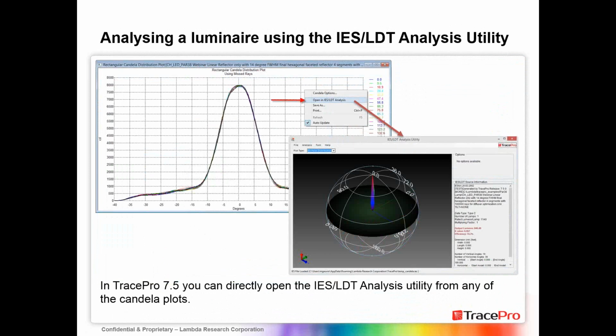Now, there's something new in TracePro 7.5. This allows you to bring up any Candela plot and right-click to get the Candela options. You'll see a new option in the list, Open in IES/LDT Analysis. You no longer have to save one and then bring it into the IES/LDT to further analyze it. By just clicking on the Open in IES/LDT Analysis menu item, boom, up will come the IES/LDT analysis utility,